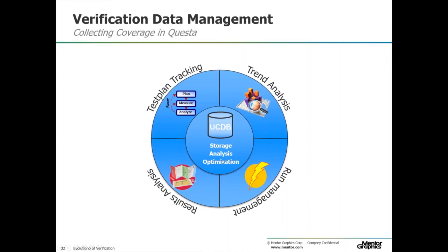Once we're storing that coverage information in there, we can actually link that to your test plan and allow you to look at how you are doing on the coverage versus your test plan. It gives some trend analysis so that you can look at how your coverage is trending over time. The results analysis is all about debugging your whole regression suite simultaneously, as opposed to debugging each failing test.